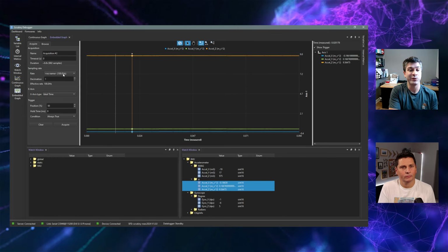I have a demo that showcases that with an RX microcontroller. It has a 10 kilohertz task, and there's some fake signal that you can go and probe, and you can see that depending on your rate, you can get little staircases or smooth values. That is worth checking. But now you don't just want to launch a value. What you want for debugging is to wait for an event.